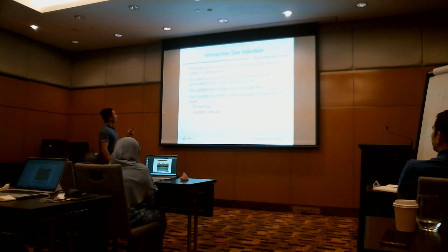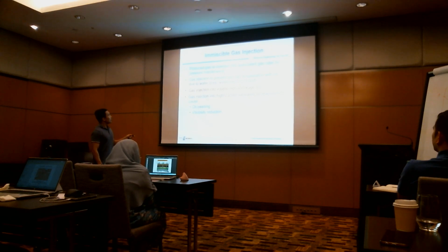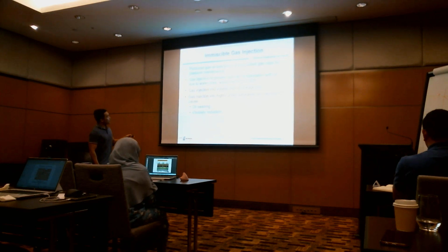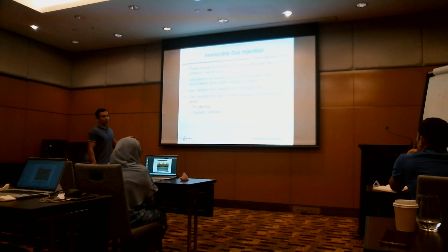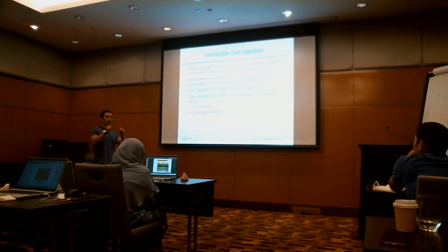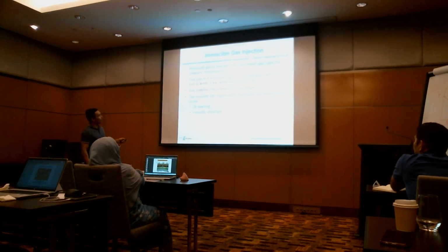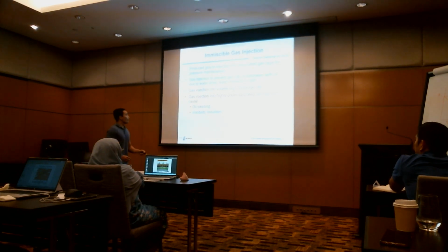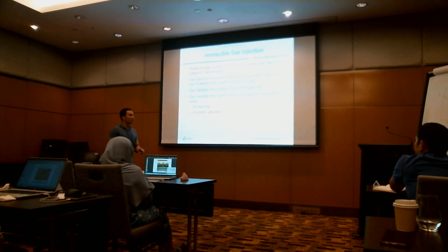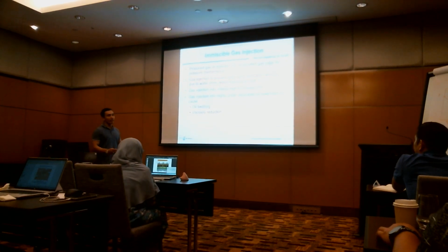Okay. So same thing, gas injection into the gas cap for pressure maintenance, like I mentioned. Gas injection to prevent gas desaturation of oil due to water drive. Remember, I said earlier, you want to avoid the oil column going into the gas cap, right? Okay. Gas injection into volatile high shrinkage oils, because volatile high shrinkage oils means it is easy to liberate the gas, right? So you want to avoid that.